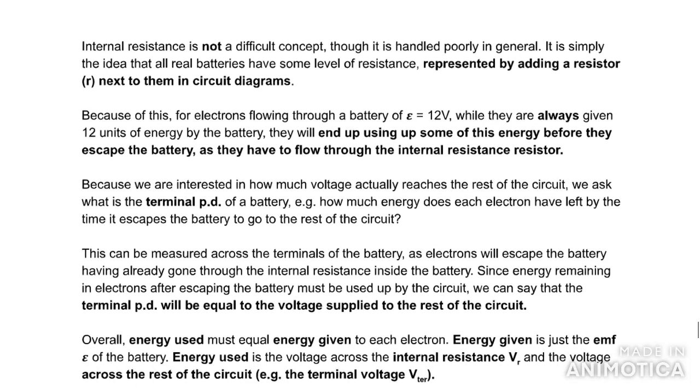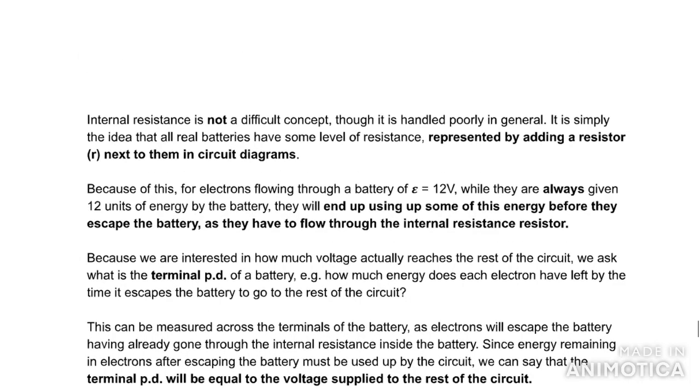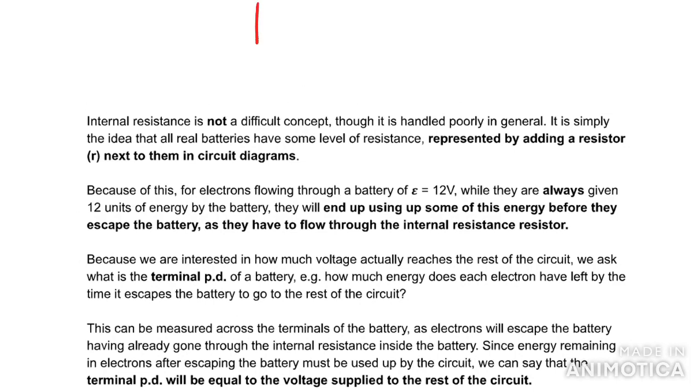Up till now, we've considered ideal batteries, e.g. ones without any internal resistance. Now we're going to introduce the idea of internal resistance in batteries because it's more realistic. Effectively, with our assumptions, if I'd set up a circuit like this with a voltage V, we said there's no resistance in this circuit. And so the current is going to be infinite. In practice, that's obviously not going to happen, so we need an explanation as to why.